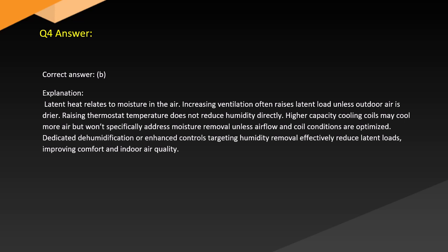Answer. Correct answer: B. Explanation. Latent heat relates to moisture in the air. Increasing ventilation often raises latent load unless outdoor air is drier. Raising thermostat temperature does not reduce humidity directly.